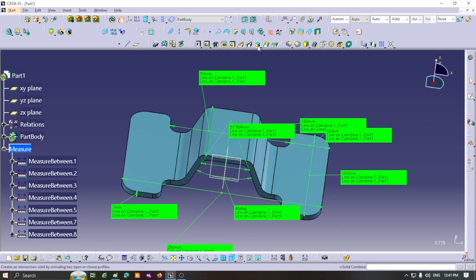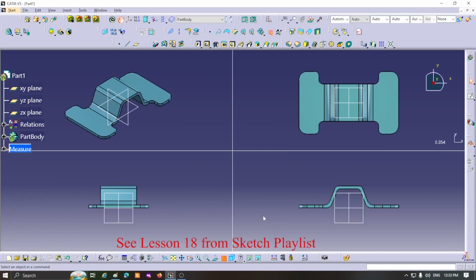The software has also provided another tool for us. This tool is very useful in certain situations. First, I position the shape in both the top and side views. In each of these viewpoints, a two-dimensional image of the shape is seen. This tool creates a volume by combining two sketches.